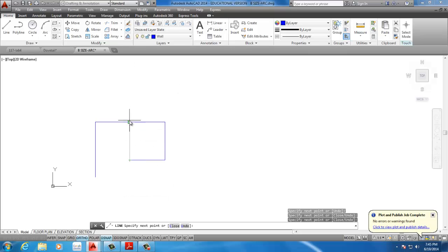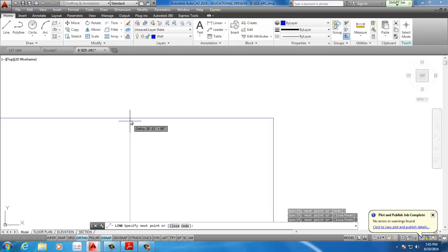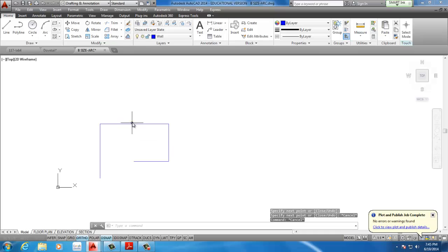If I move my mouse down, you see that symbol. So it will snap onto that location, making these lines attach. The other symbol you'll see next to it is the triangle. Since I drew the line in a way, I can actually extend this out. If I want this line to be at the center of this line, you'll see the midpoint, which is right here, the triangle.